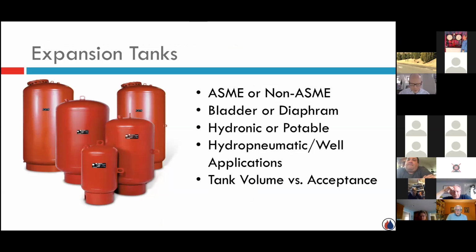Potable water became popular when the codes changed and we had to start putting in either check valves or, more commonly, backflow preventers on our cold water line that's coming into the house off of the city main, because at night, overnight, when say we took showers and then we heated the water and there was no more use, and that heated water expanded, pressure would start to build. And as that pressure built, it would just back its way back onto the city main.